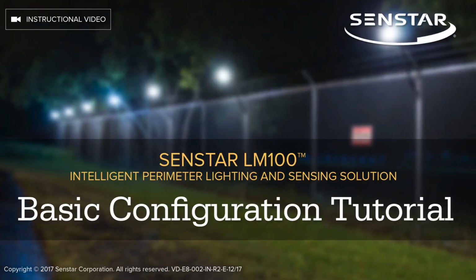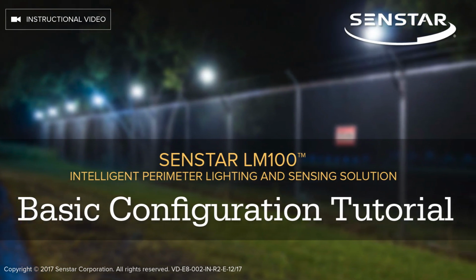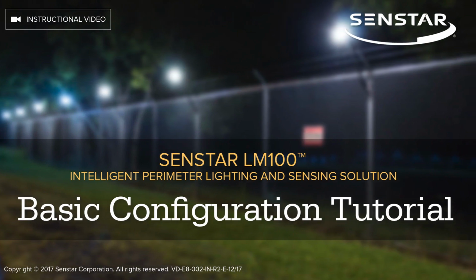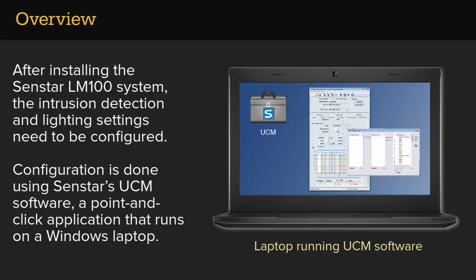This video explains how to configure the basic software settings on the Senstar LM100 in order to get it up and running. After installing the Senstar LM100 system, the intrusion detection and lighting settings need to be configured. Configuration is done using Senstar's UCM software, a point-and-click application that runs on a Windows laptop.